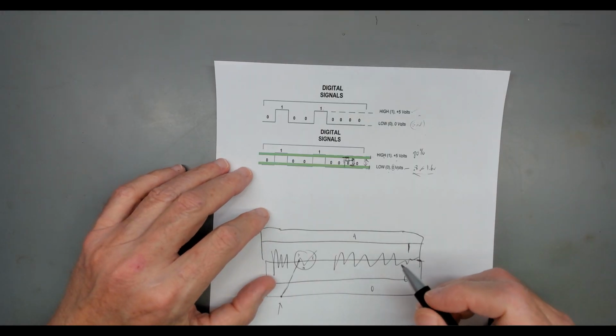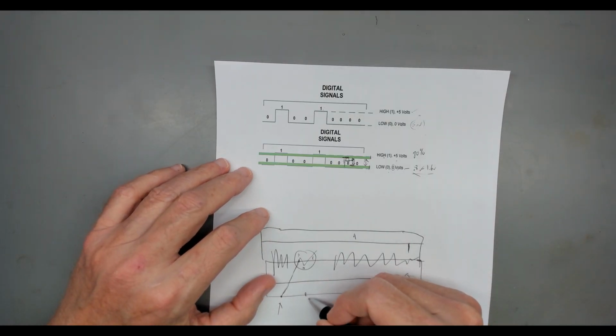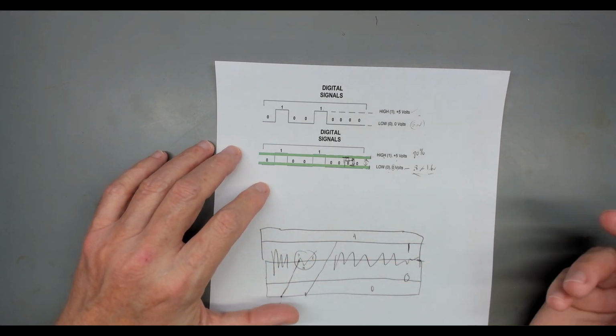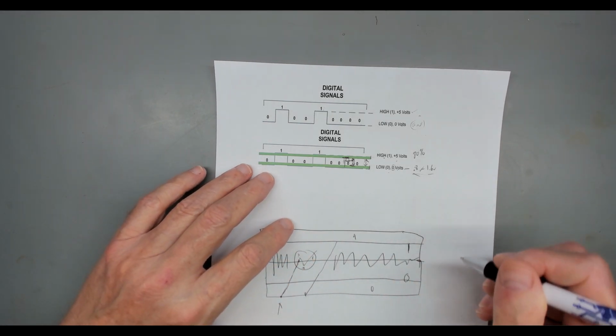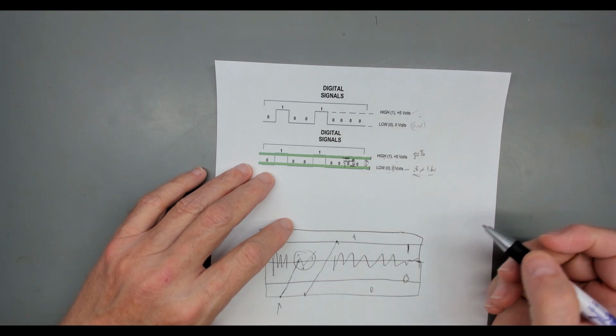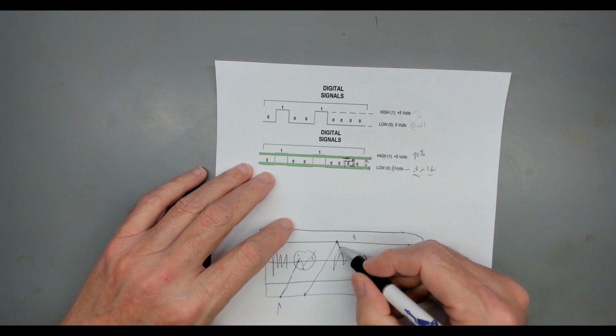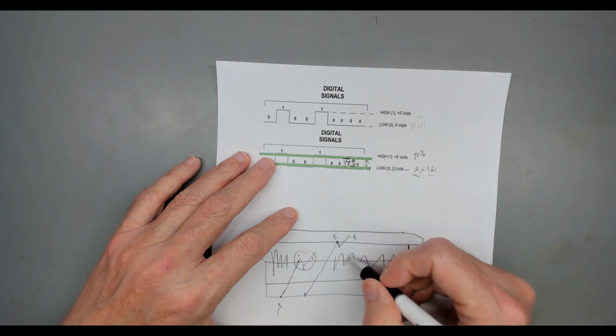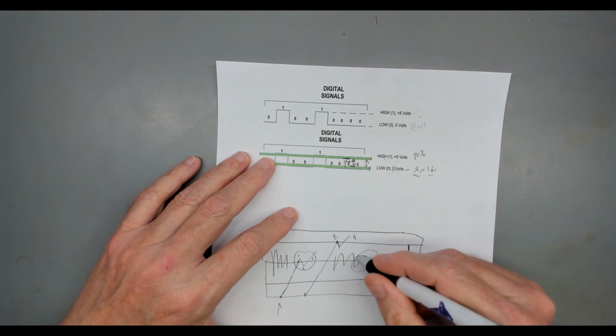Now let's take our scenario. Let's start from 0 and we're going up to become a 1, but we have to go all the way up to this line at about 80% of our supply voltage. And we get here and we get stuff turned on that sags the voltage. It drops down in this range and then it goes back up. It works perfectly. And here's why. When it switched to 1 right here and then sagged in here, in this area, we don't change.